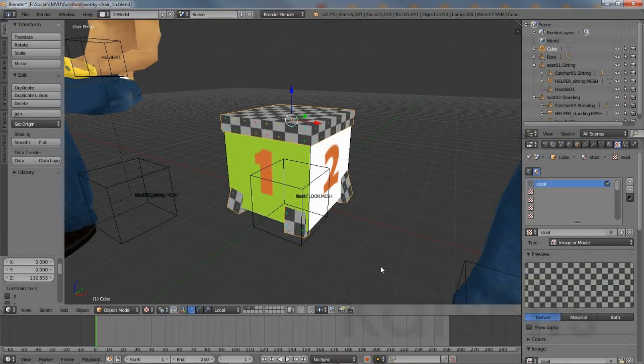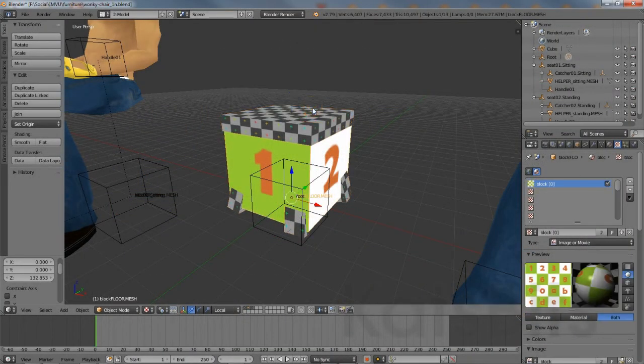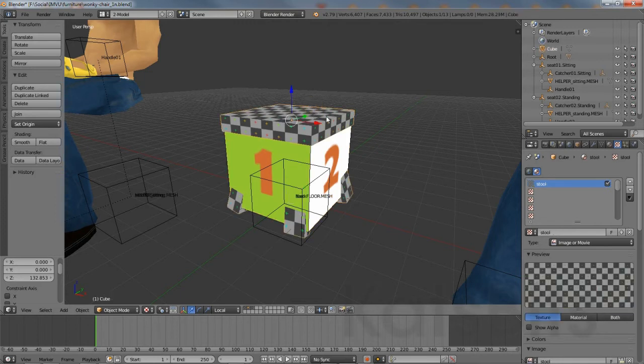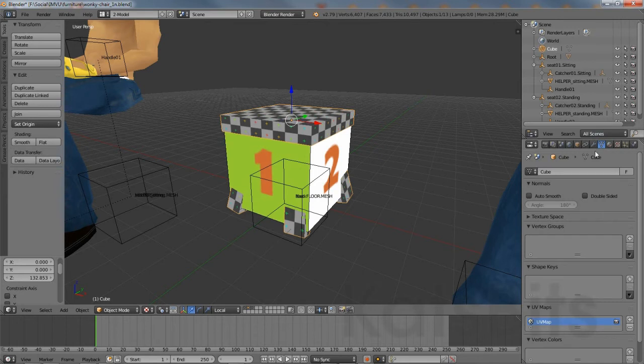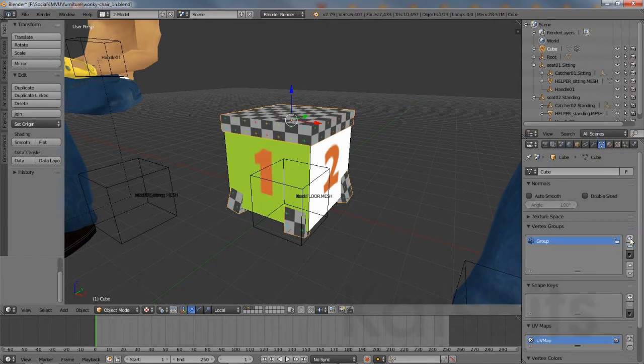Once positioned and reset, with the object selected, right-click, left-click the Object Data Properties button. Here, in the Vertex Group subsection, left-click the plus button to the right of the aperture. Group will appear. Double left-click the entry highlighting the text for editing and type root, uppercase R.